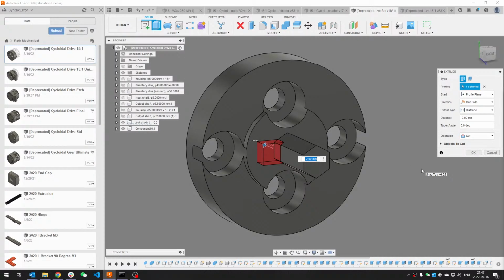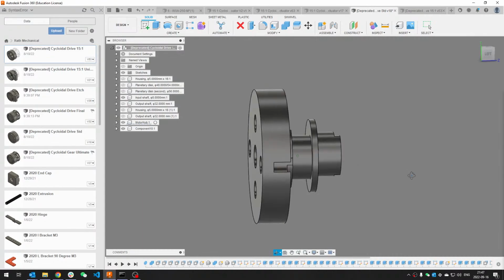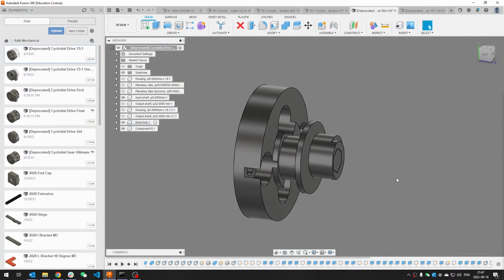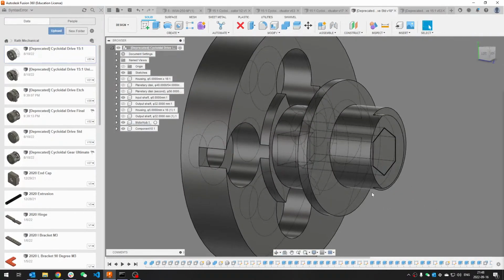Immediately after putting some load, it becomes a round rod, and it just starts to rotate within the input shaft of this one, the cycloidal generator. So then I added this square thing here, which acts like a key to the shaft, and that helps a lot. So I'm using this design moving forward.